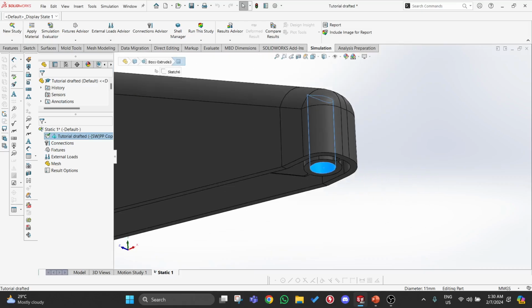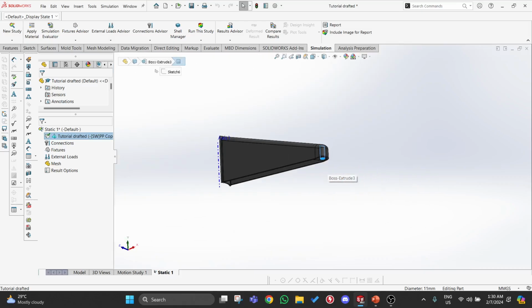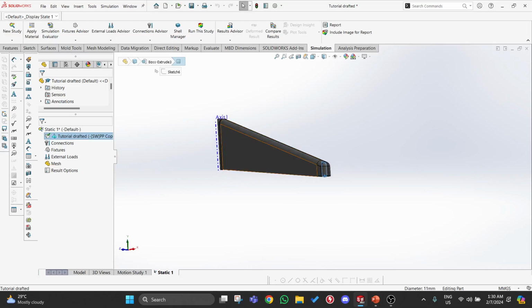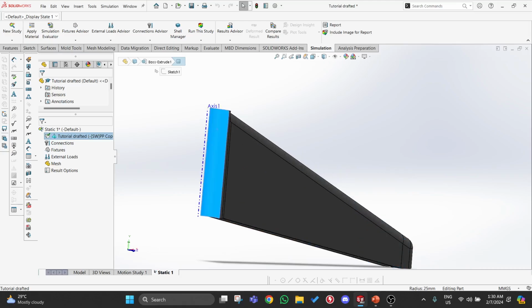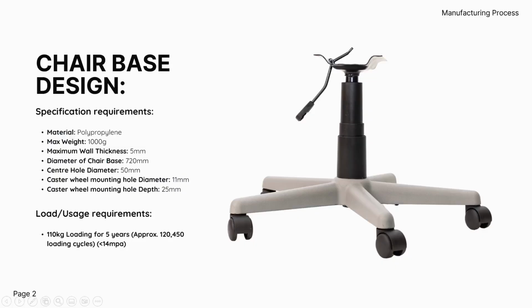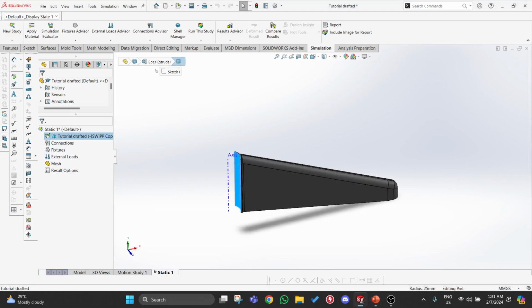This part here is where your force is going to be distributed. It's going to be pushed up, and your chair is going to bend upwards, right? It's going to flex upwards and displace. And then this part is where your hydraulic press is, and it's going to be an immovable object. So it's going to be a static object, because that is where your reaction force does not move, right? Because this is a perfect simulation, so we do not count things like twisting or anything else.